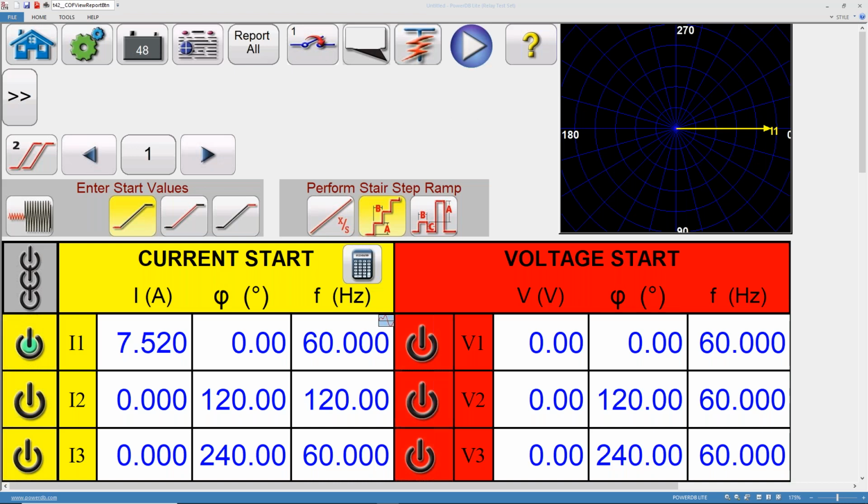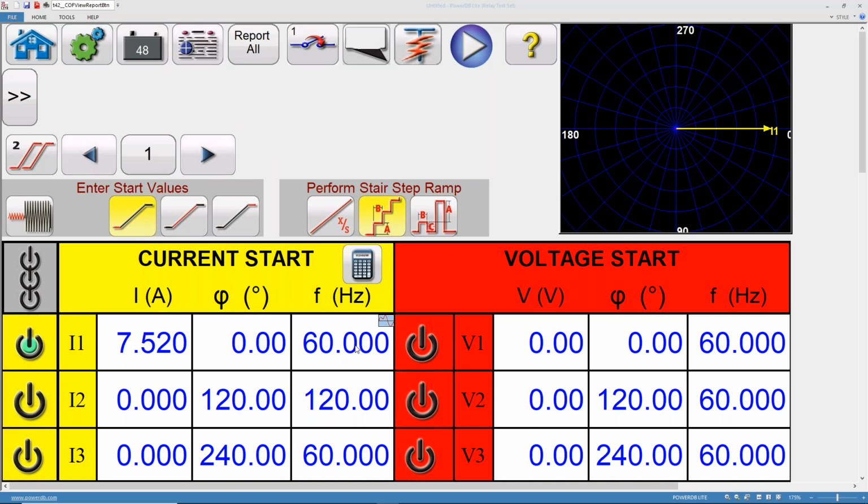What's really nice about doing the harmonics test with RTMS and an SMRT unit is that we don't have to use two generators. You don't need to stack two generators, so we don't need 4 cables to tie to this relay. We can do everything that we need to do using the single current generator. The single current generator is going to apply our fundamental frequency along with a 120 hertz signal, stacked on top of the fundamental frequency of 60.